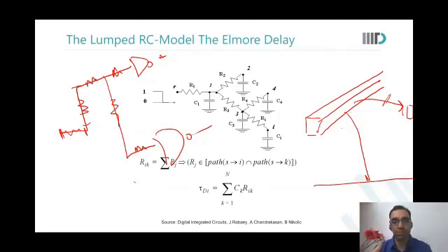Every via, it says, now the new wire has started. So I will model it separately. A new capacitance comes into picture, a new resistance comes into picture. Every turn something happens. So that is distributed RC. And you can imagine how many resistances. If you are making just a simple inverter, how many RCs will come into it just because of metal one. You realize this?